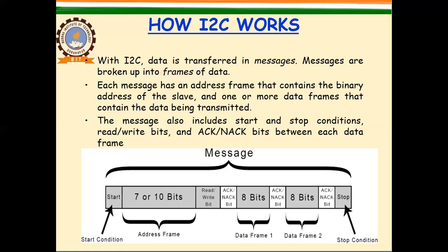The message also includes start and stop conditions, read write bits, and acknowledgement, no acknowledgement bits between each step. The message also has start and stop conditions, whether it is to be read or written, and there is an acknowledgement bit also, which is missing in case of SPI.